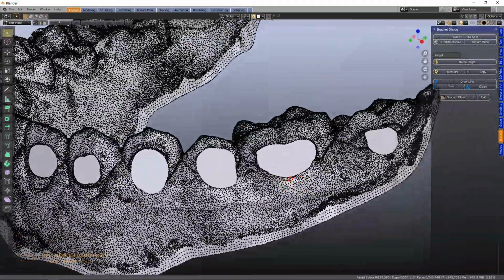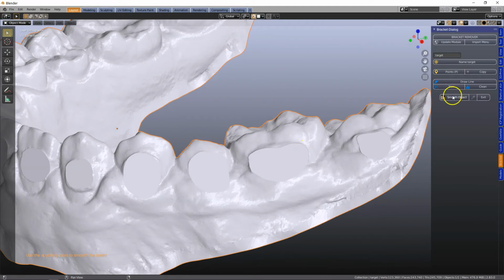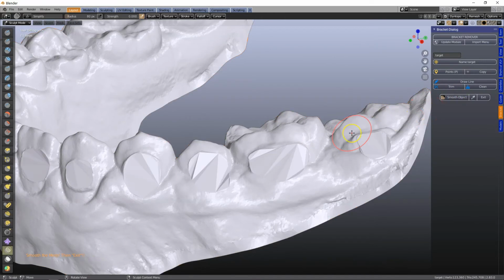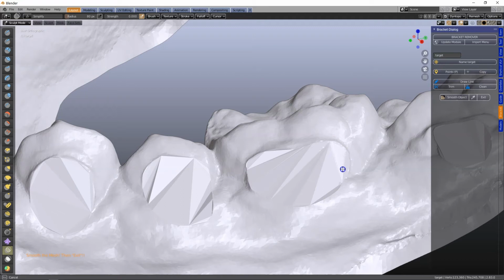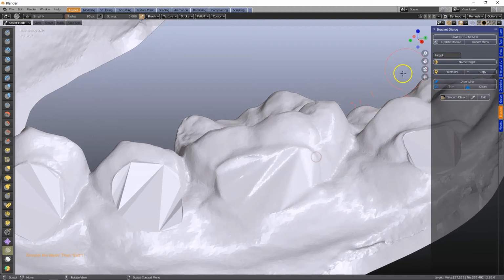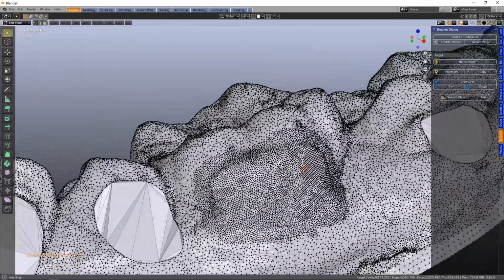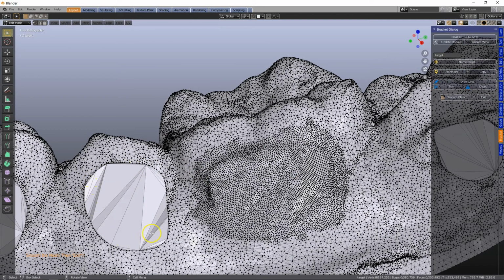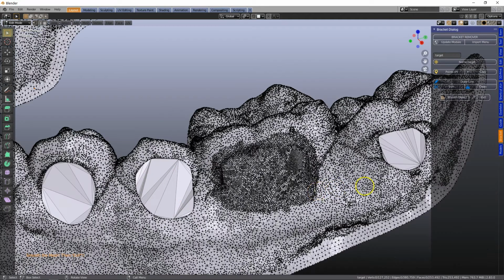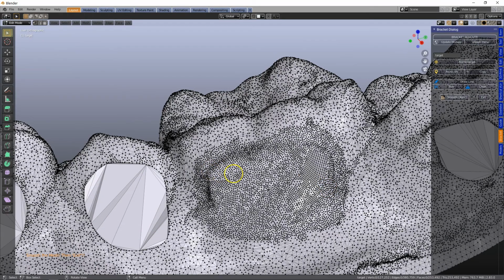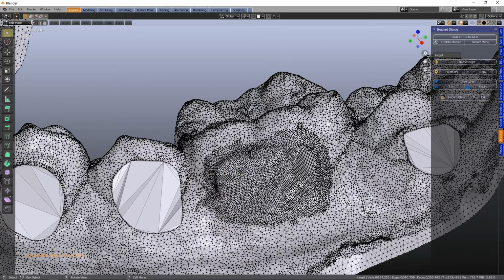So in order to avoid that, we will click on Smooth Object, and then we can give it a quick brush over. So please note that we have something called Dynatopo here. So if I go into edit mode, for example, just to inspect the mesh, I've got a nice clean mesh as opposed to its neighboring teeth. So this is what we want to strive for.